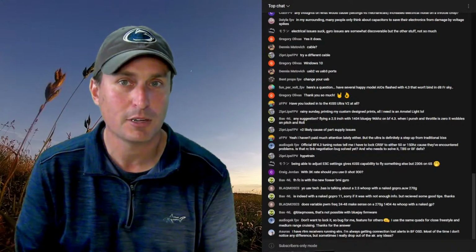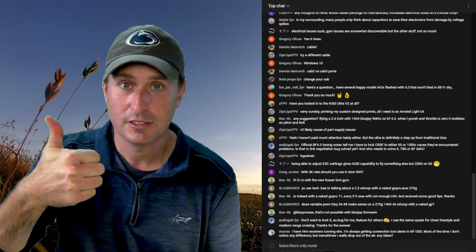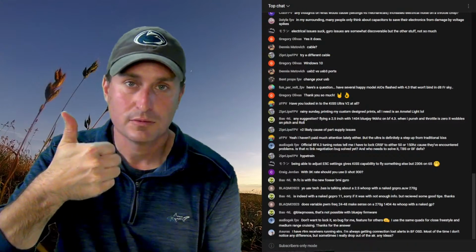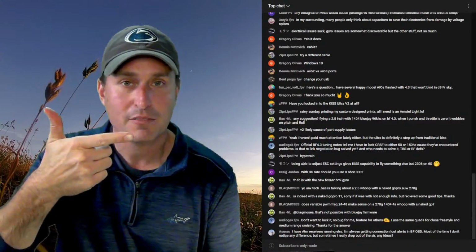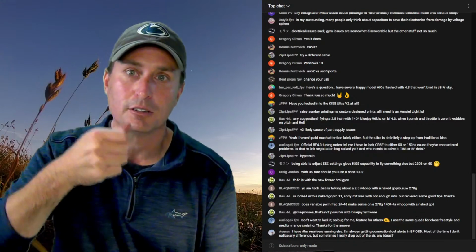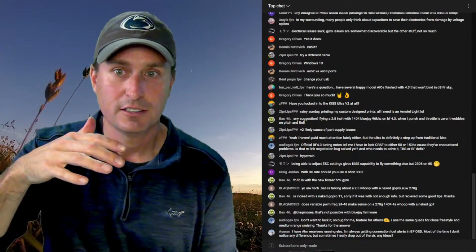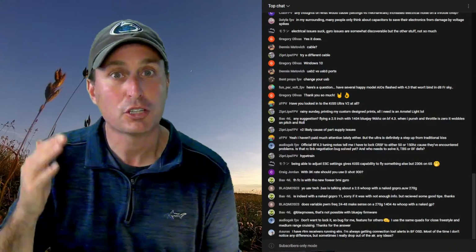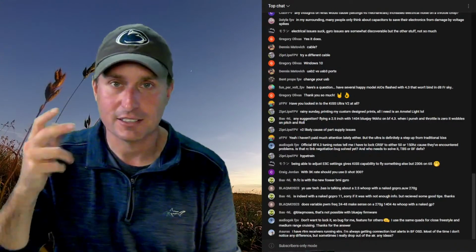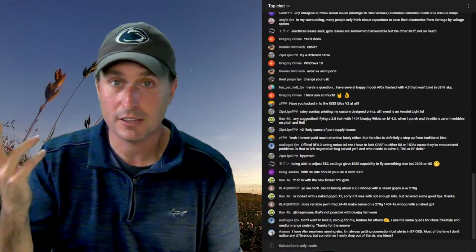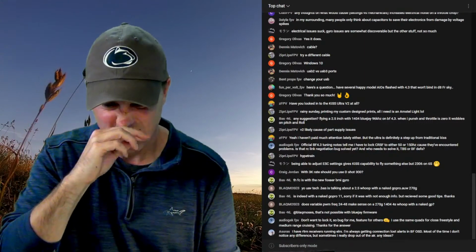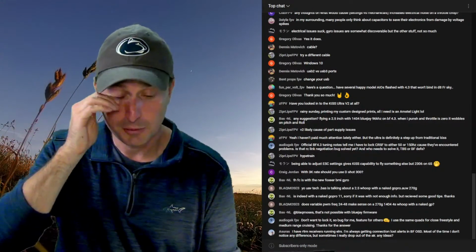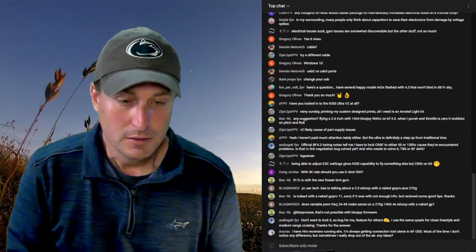The only reason I would go up to a higher PWM frequency is if you have electrical noise issues, which I don't, because I don't use gear that has that. But if you have electrical noise issues, then try a higher PWM frequency. Or if you have mid-throttle oscillations, like as you're going up through the throttle, you see it start to shake a little bit near mid-throttle. It could be because of the ESC aliasing stuff, so then try higher. Other than that, there's no reason to, so I would just leave it. You want it as low as you can, like golf. That's my advice.